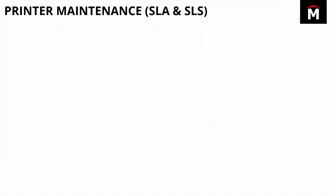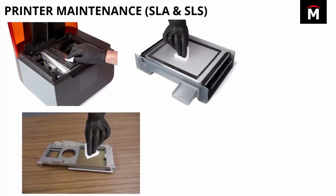Now with SLA and SLS, you can join these together because Formlabs told me that 80 to 90% of print failures are a result of dirty optics. So you want to make sure your optical window is clean, your tank film is clean, the optical set, if you have a fused SLS printer. You want to make sure all these are clean so that the laser can easily pass through without any kind of occlusion.